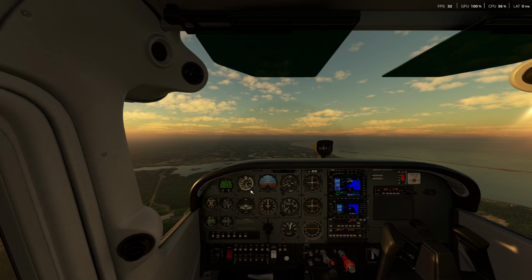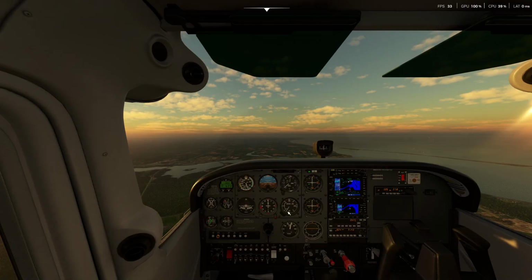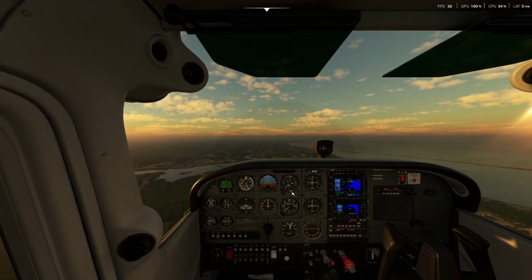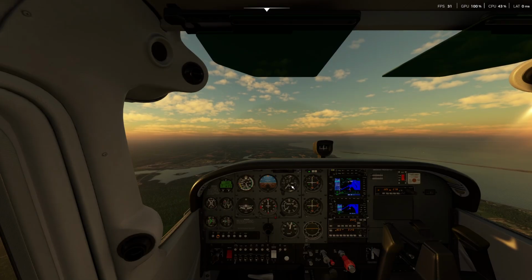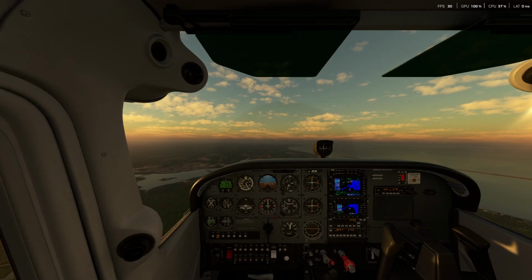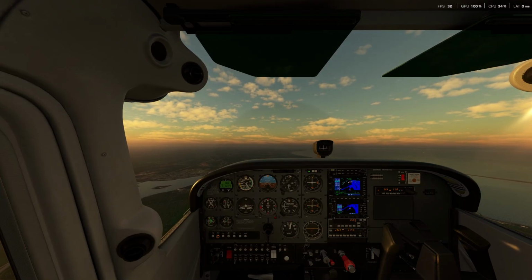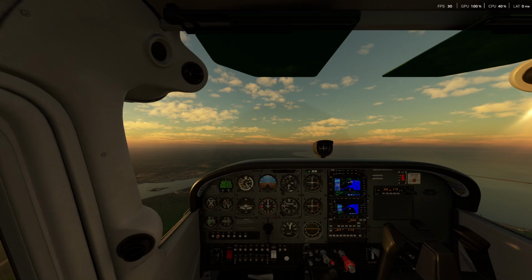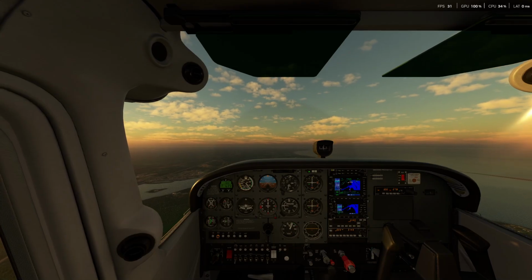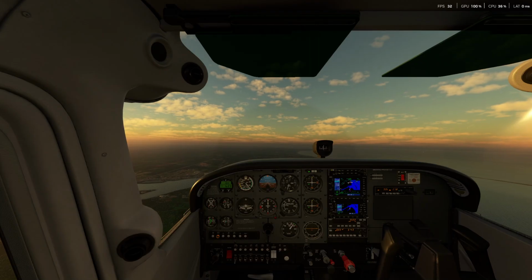One thing you can see is that your vertical speed is showing a decrease, about 700 feet per minute right now. Your altitude is also decreasing, counterclockwise rotation showing a decrease in altitude. So at about 2,500 feet, we'll go ahead and level off. We go back to about 2,300 RPM, and do the opposite of that so we can climb.